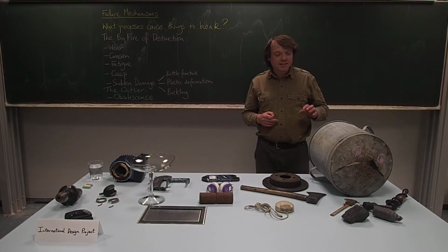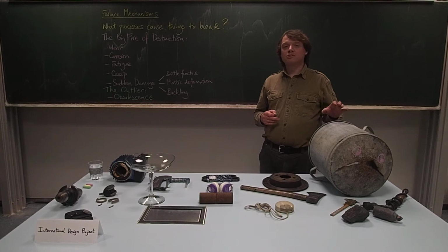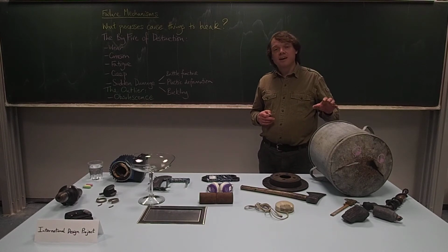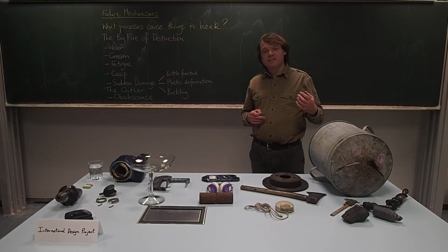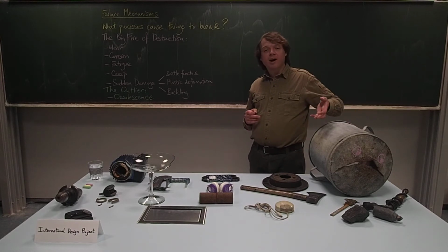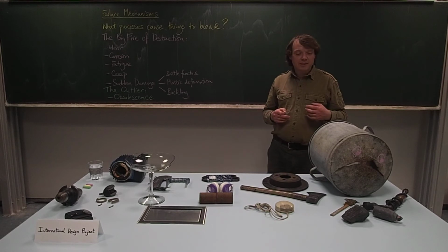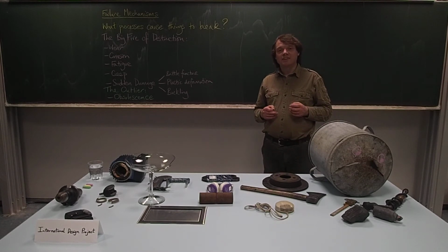The answer is presumably that only the bottom of the bucket, where the zinc layer, probably through mechanical wear, has been damaged, has been kept wet. And that means that the electrons which have been taking part in the corrosion process haven't been able to flow up the sides here and corrode the zinc.